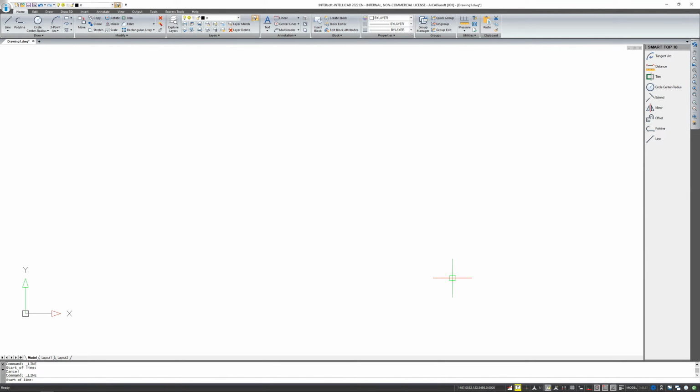So you do not enter absolute coordinates from point 0, 0, which is denoted by default in the lower left corner here, but from the point where you click. If you wanted to start drawing as absolute, you have to turn this box off, which I'm doing now. So here at the bottom, in the status bar, I'll turn dynamic input off. And I'll introduce the first line in such a way so it will start from point 0, point 0.